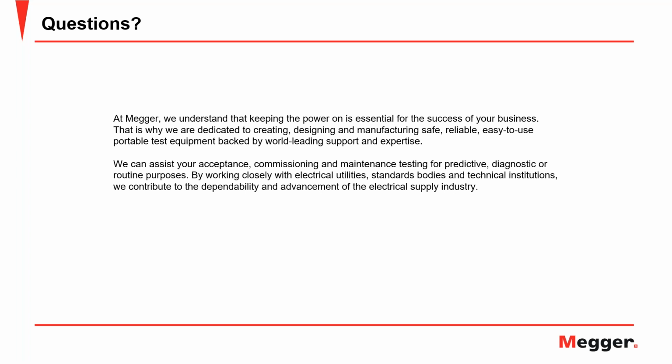Thanks, Ken. Sanket, if you are doing the VDF test, is it still necessary to do the regular power factor test? Yes, so VDF is a factor which is provided to you by the software when you do a regular power factor test. So let's say I was testing a transformer and I ran a regular power factor test. That's when I'll get the VDF right there, and then based on that value, if I see a high value of VDF, the next step would be to do a tip-up test. So VDF is not a separate test in itself. VDF is a parameter which the software provides to you when you do a regular power factor. And based on that value of VDF, you can decide whether you want to do a tip-up test or not.